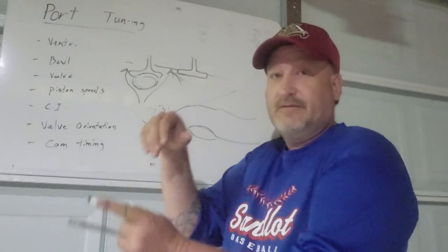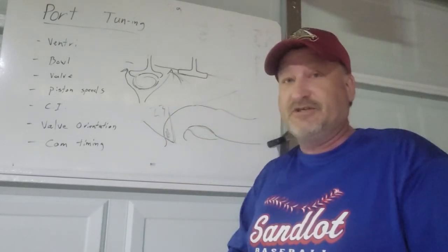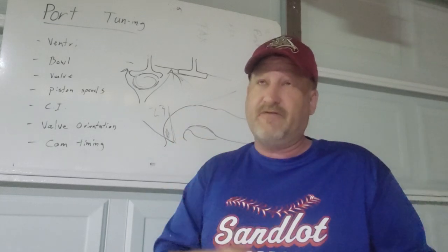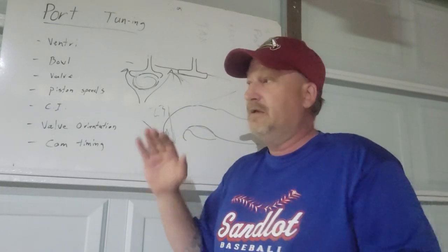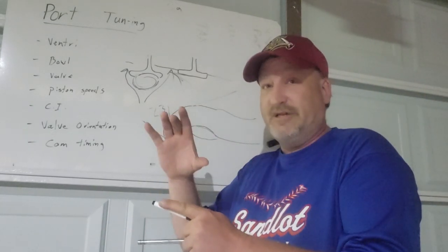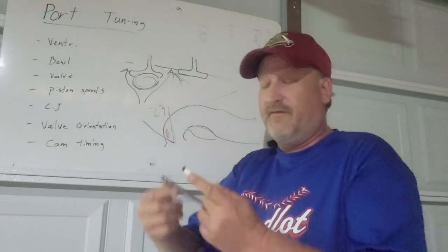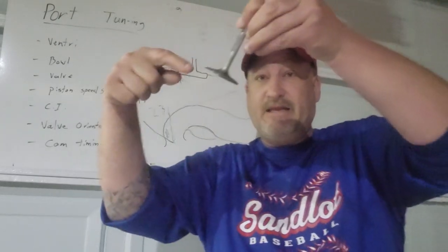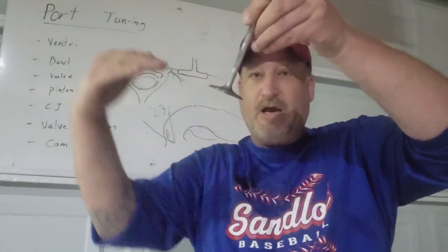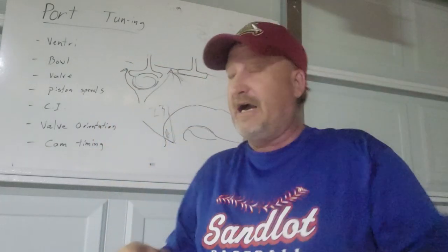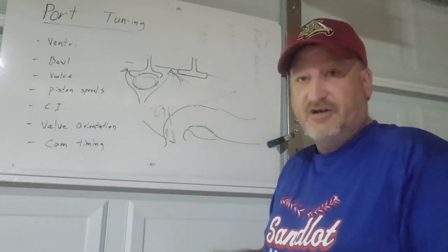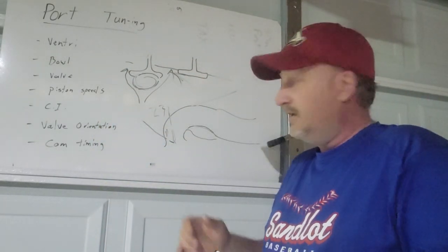They're conjoined. Okay, so with the LS engines, with the exception of the LS3, the port entrance and angle to the valve angle is to address the air and the valve moving outside of the actual highest velocity region of the port. It is not a direct relation.